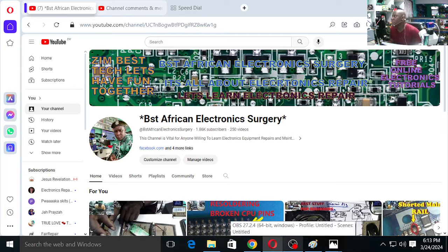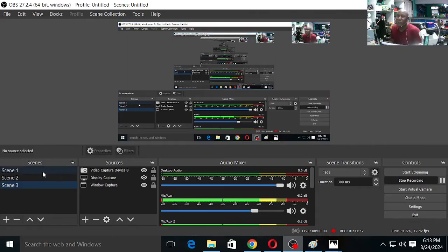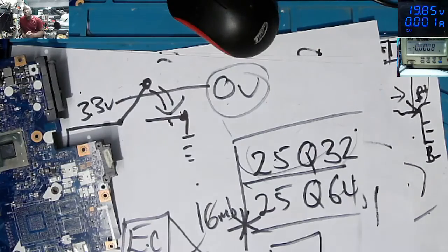I don't recommend the spirit, because the spirit's rate of evaporation is very low. So if you test the board fast, bad things can happen, as compared to isopropyl alcohol, which evaporates very fast.